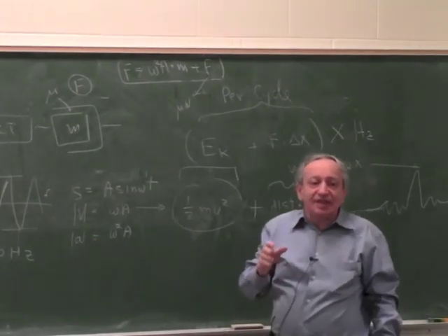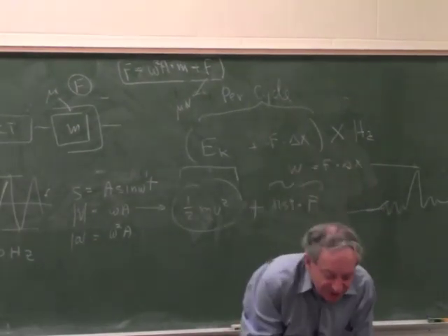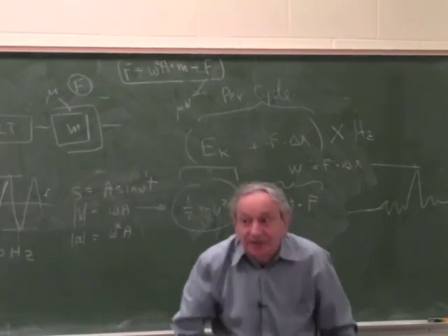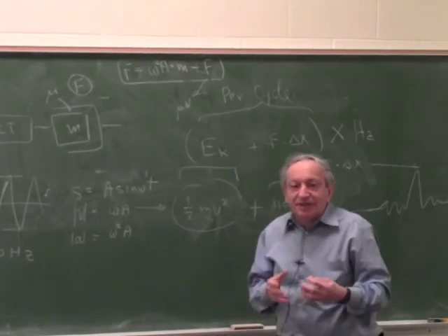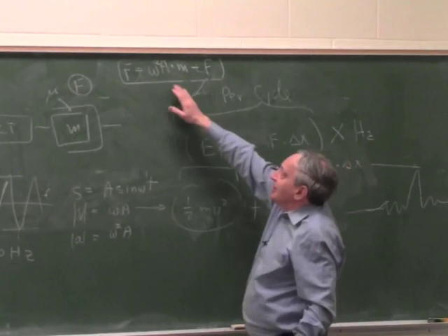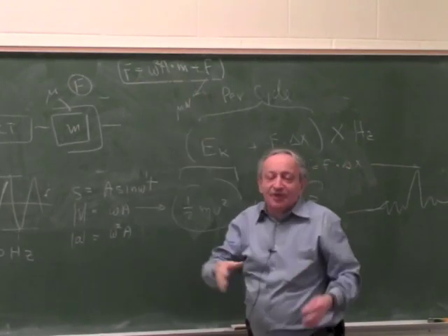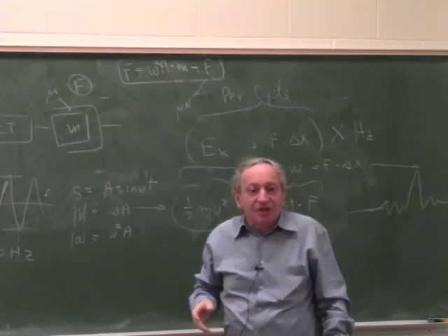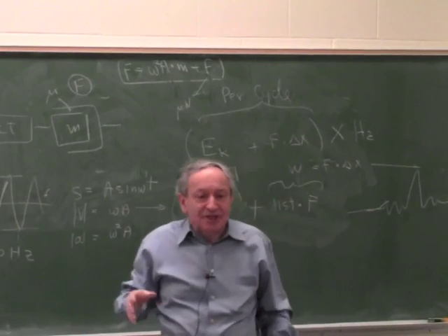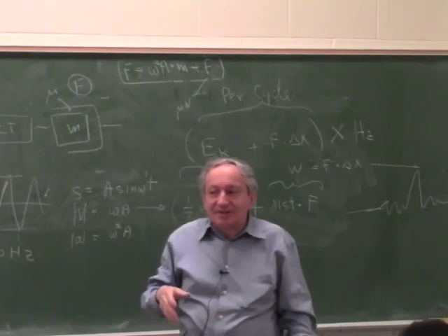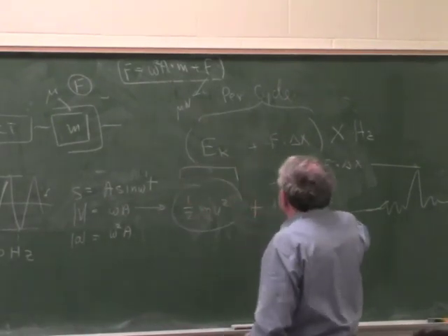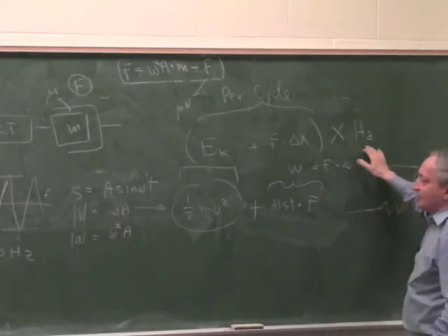So if the actuator is limited by force, if that's a weakness, it's easier to do it this way. Calculate the peak force, compare it to the data sheet of the actuator. If you're more worried about energy, say motor getting too hot, then you should calculate the energy per cycle times the hertz.